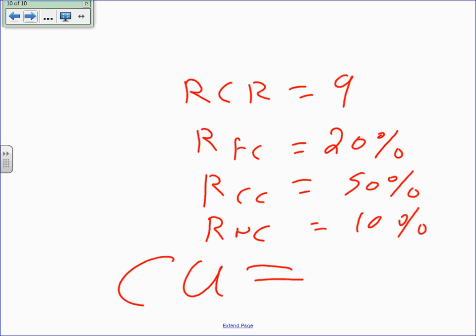Okay. Can you just see the RCR? The first number is 20. I have no other option, right? The second, I have 50. The reflection from the ceiling is 50. Everybody can go to the other set of columns, 50. RCC is 50. Now the walls are also given as 50. So go cross-reference 50 with 9. Anybody can give me what the answer is? 0.29. I'm giving you a room cavity ratio of 9.